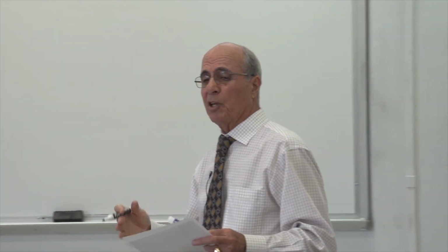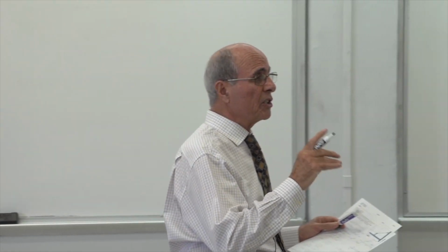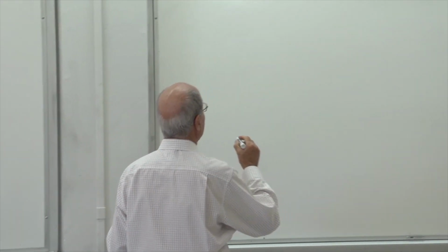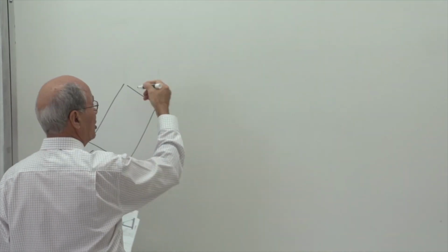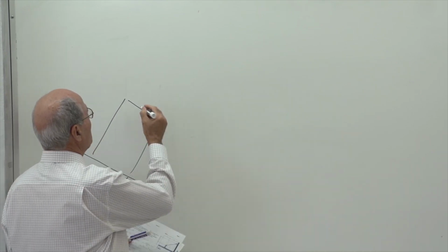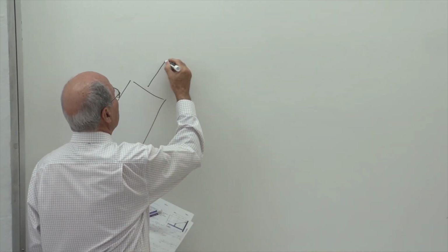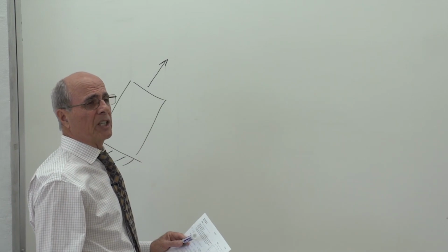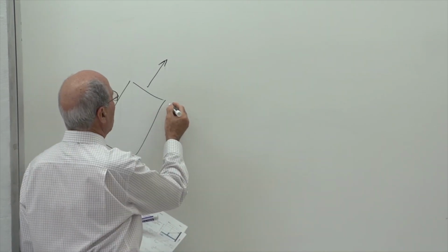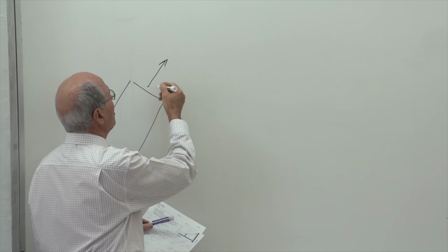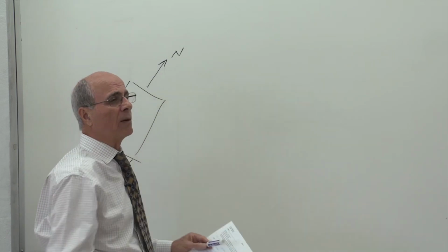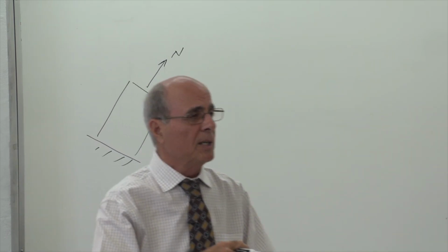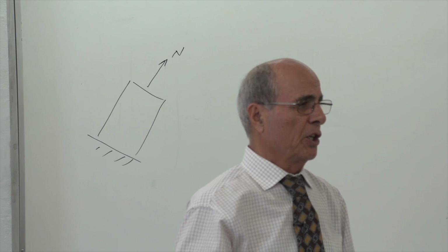No other member can be touched yet there. Not yet, because we don't know yet about the bending. This is the idea that still the students do not understand. When we come to a rod or a cable which has a cross section like that, notice there could be 3 rods. This was explained in the first lecture. If this is point A or B, we don't call this anymore Fx or Fy. We call this one normal force. Why normal force? Because it is perpendicular to the cross section.